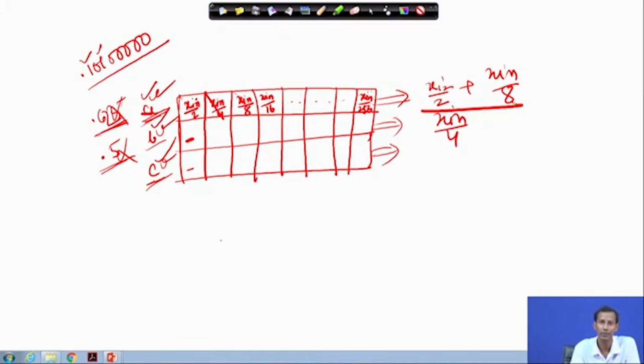If I want to do this multiplication operation in a shift and add based method, then when all these positions are 1, I will get the maximum number of terms for the addition operation. Each of these is ANDed with the corresponding values of A. This particular position is ANDed with the corresponding values of B. So, for A into x_in, what is happening?